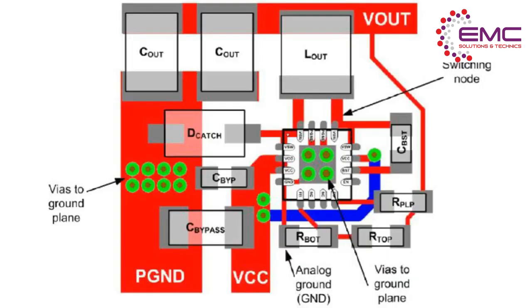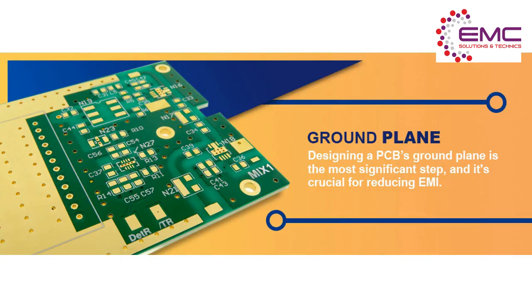Now we will discuss the guidelines, how hardware engineers can address EMC issues during the PCB design phase to achieve a system free of EMC faults. Ground planes. A low-inductance ground system is the most vital element when designing a PCB for minimizing EMC.